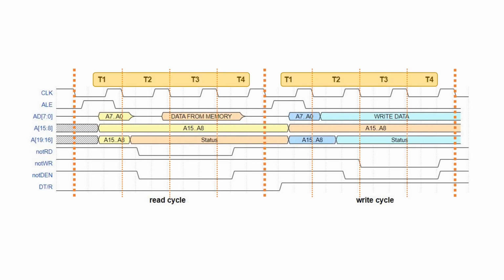Again, this is just to make a clear highlight that the read cycle is 4 T states and the write cycle is 4 T states. The blue line's been added just to illustrate where the address gets latched. So the CPU outputs the address on AD7 to 0, and while ALE is high, the 74LS573 or equivalent is transparent, and whatever is on the AD pins passes straight through.